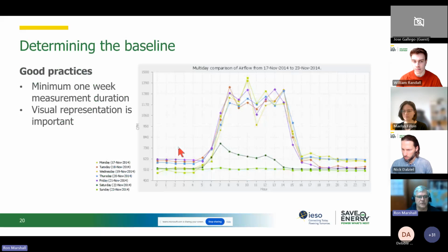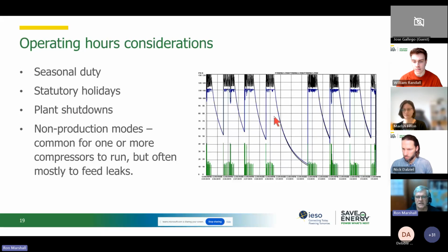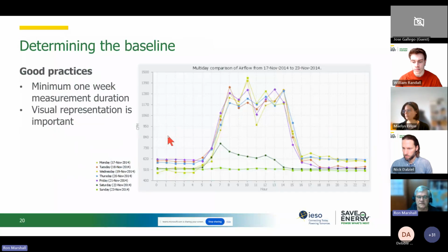All right, so if we wanted to do leak testing, and we're going to talk about that a little bit later, we would maybe be doing it at the end of a shift or on the weekend or something like that. And sometimes compressors are left on when they're not required, right? So one plant that I recently went into, they only have an 8-hour shift, don't work on the weekends, yet they leave the compressed air system on 24/7, even during holidays, right?